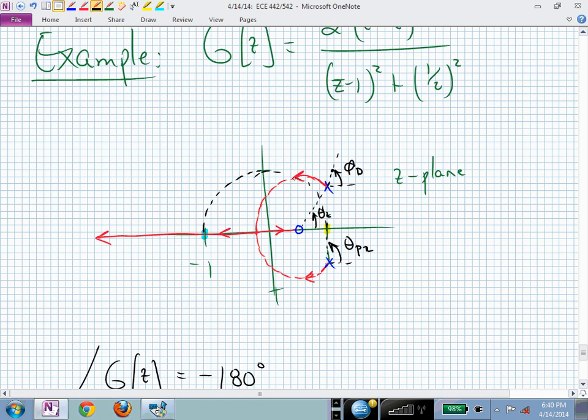Now you want to know what gets you to that point. We've just learned what happens at that cloud. That's where they re-enter, and this is where they go unstable again. And you could compute the gain to get you to those three places. Graphically might be the quickest if you sketch these somewhat reasonably accurately with maybe some grid paper. Do you see what I'm saying?